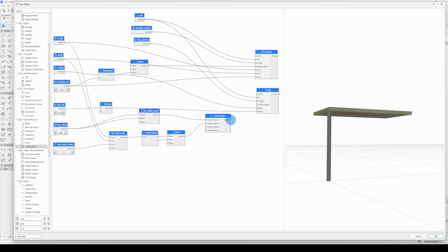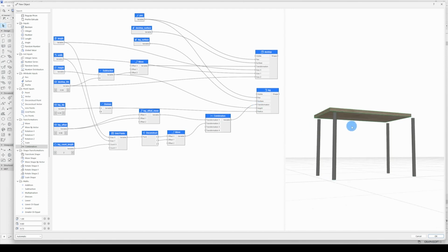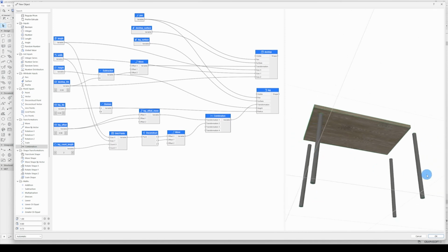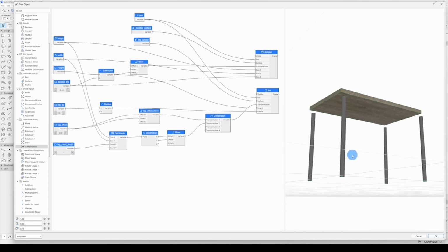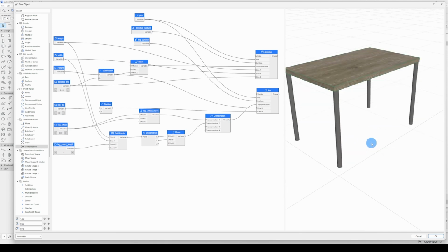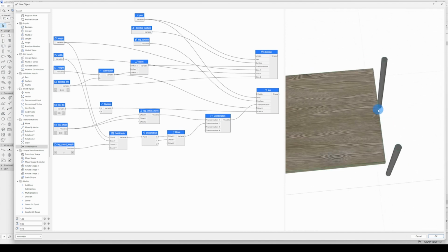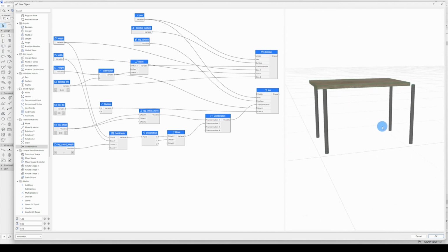Now if I put that output combination into my transformation, it's offset my leg and it's run my array, my grid points. But now you can see the problem I'm faced with is that it's taken the entire length of the table and offset. So this is poking out the distance of my offset. So I need to correct that.